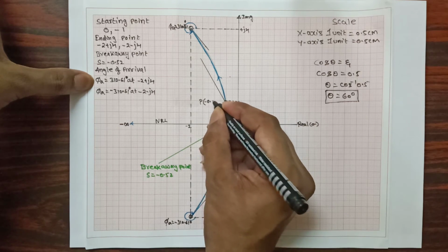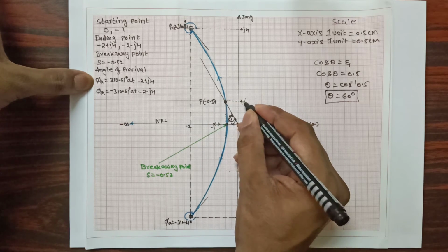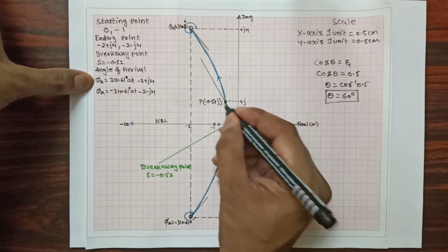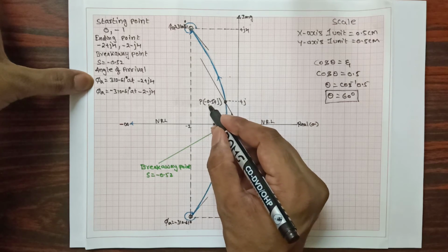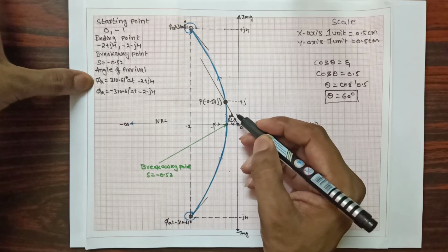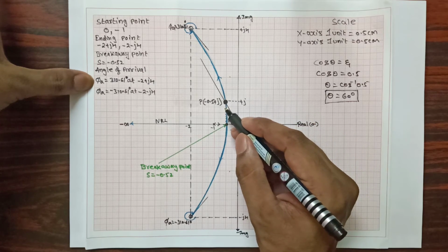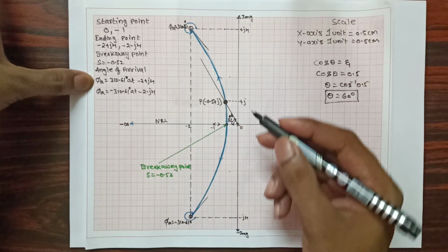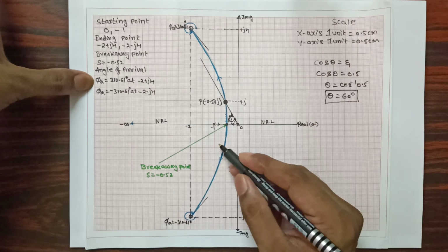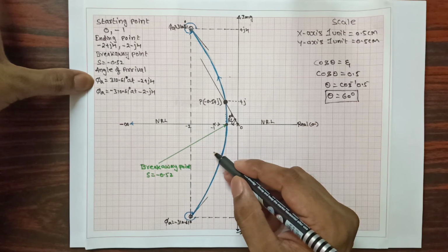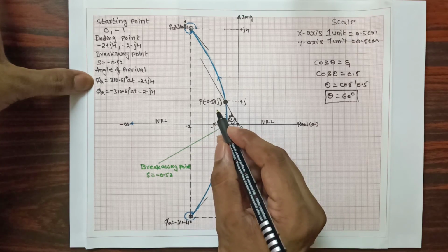So minus 0.5 plus j1. This point I am naming as point P. So the value I got here is minus 0.5 plus j. In this way we are going to find the dominant poles. Now for this pole I am going to find the K value. The same, if I draw the 60 degree angle in the lower half, then I am going to get the point minus 0.5 minus j. So now we have calculated the dominant poles.